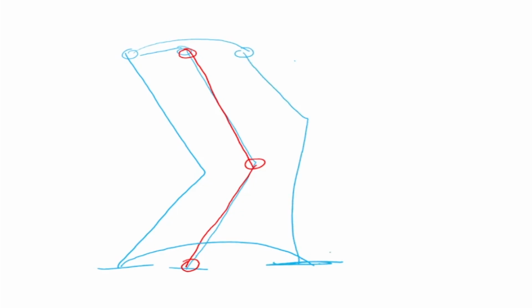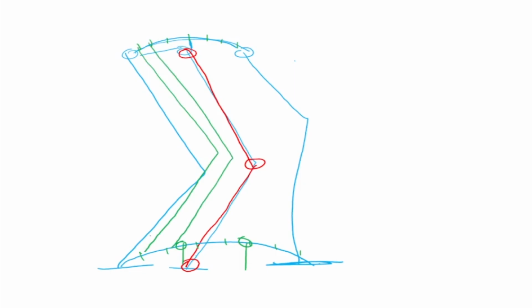So what we are saying is that this hip trajectory I'm keeping fixed, and correspondingly I'm dividing this into 20 points like this. So I find 2 of these heights, fit a trajectory, then divide into 20 points, and each of these points correlates, right? From geometry I can find what those angles are, and I take the motion from one point to another and find the total work done, the total torque, which is acting, tau d theta dt. That's what we do. So for one trajectory, I get the total work done.